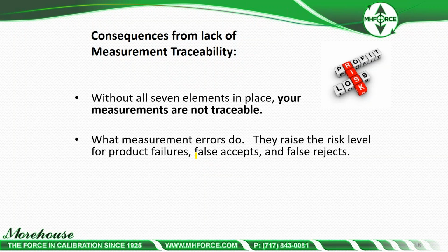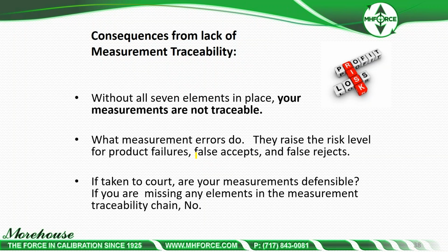What measurement errors do, they raise the risk level for product failures, false accepts, and false rejects. I suggest anyone that wants to know more about this read the measurement risk paper or take our webinar on measurement risk. If taken to court, the question that you have to ask yourself, we are a very litigious society, but you have to ask, are your measurements defensible? If you are missing any elements in the measurement traceability chain, they're not.